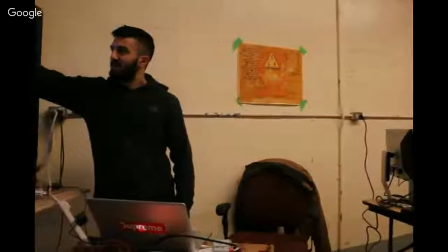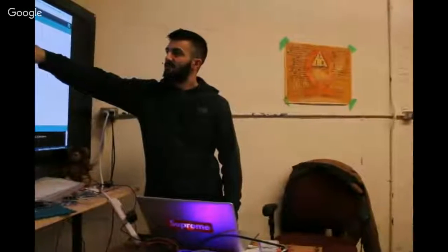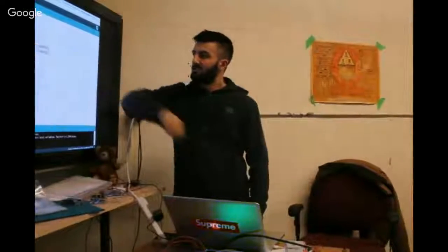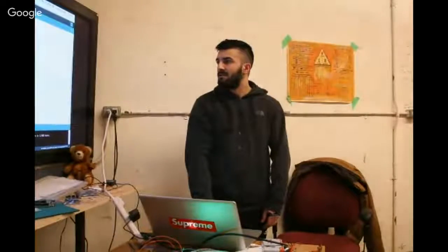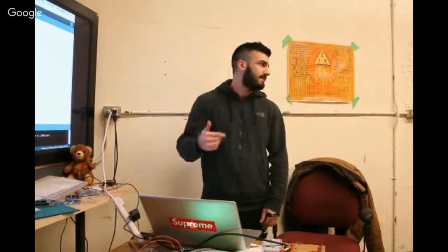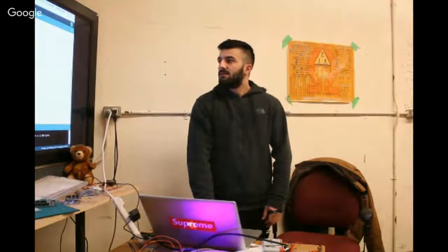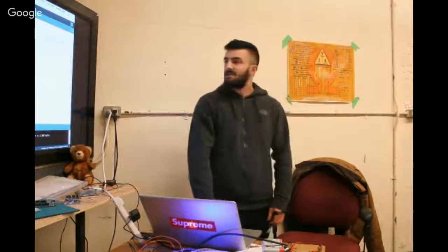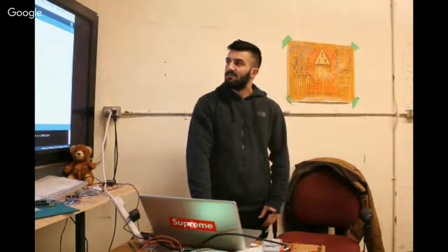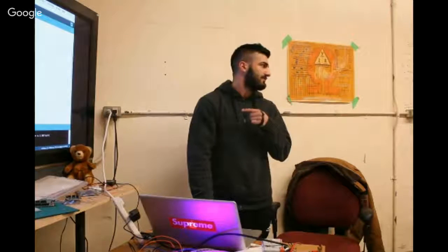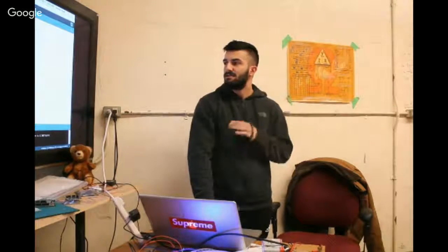So yeah, every time 5 minutes passes, I want it to jump up to the function fan off. You see the function up here, fan off. It's just a calling method. Serial begin allows me to put output statements so I can see if the code is running correctly on the serial monitor. Yeah, that's correct. If you see here, I have a fan off function just to know when it's going there, and also here, and other spots in my code.